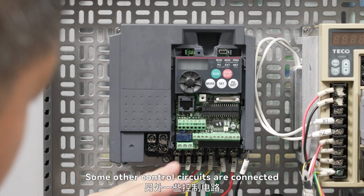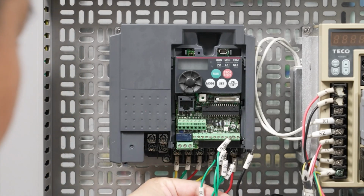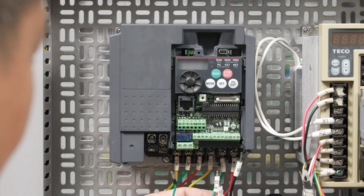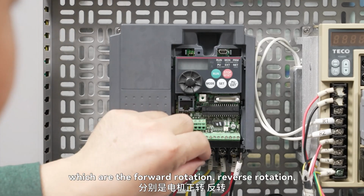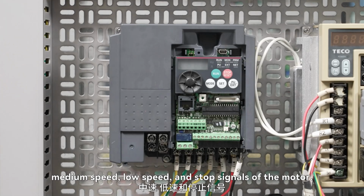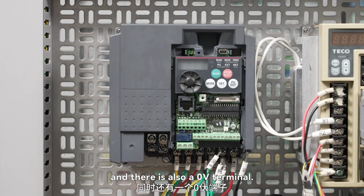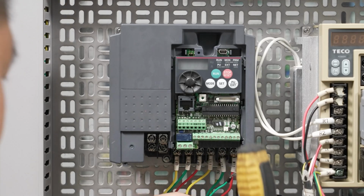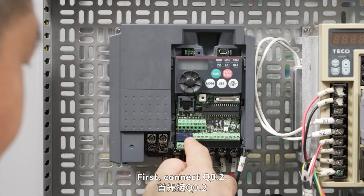Some other control circuits are connected through this row of terminals. A total of 5 terminals are used here, which are the forward rotation, reverse rotation, medium speed, low speed, and stop signals of the motor. These signals all come from the PLC, and there is also a 0-volt terminal. First, connect Q0.2.